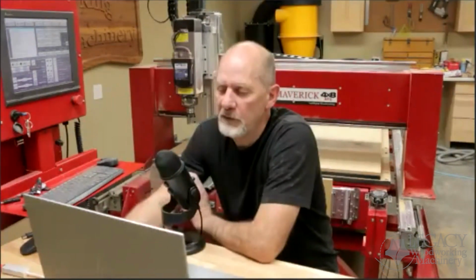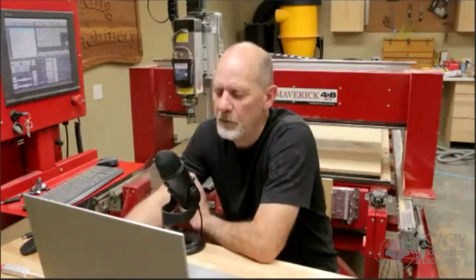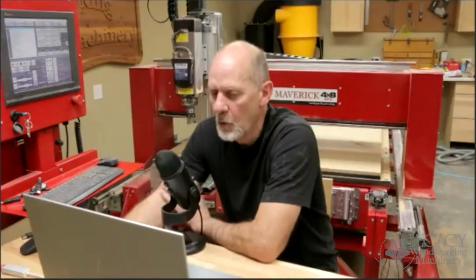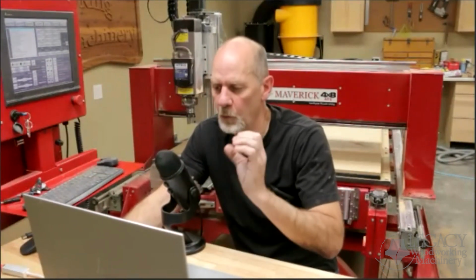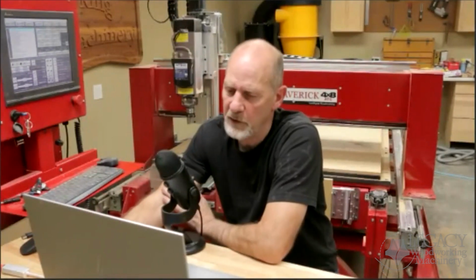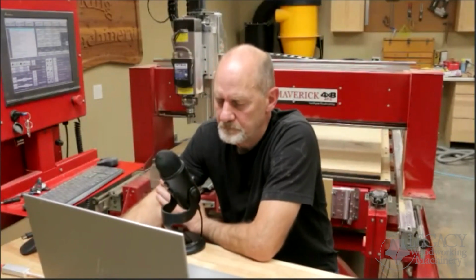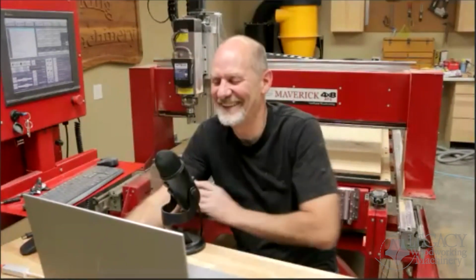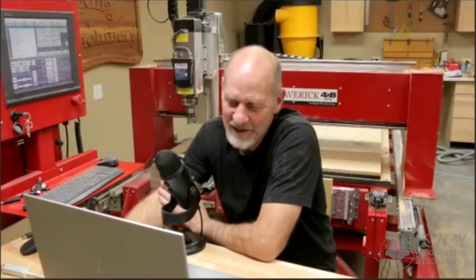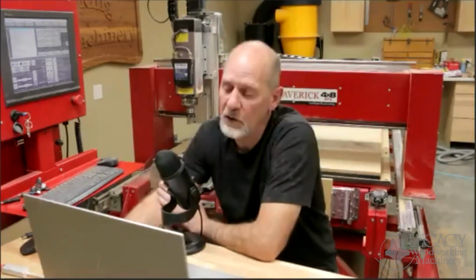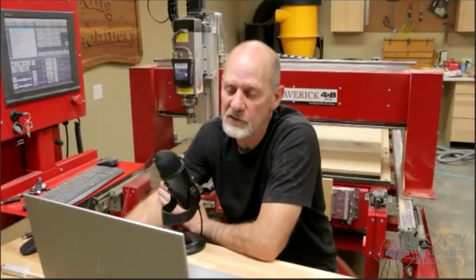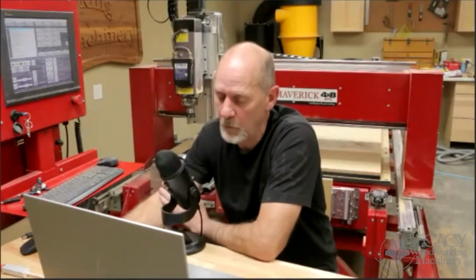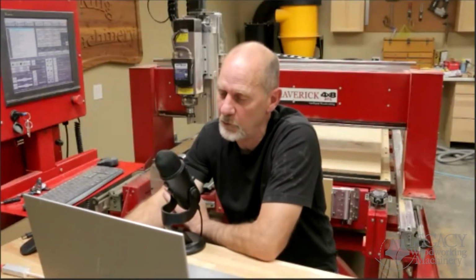This program, if you're using Mach 3 or Delta, will set the A-axis to 0 at the beginning of the program. Wherever you have it set, it will set it to 0. It doesn't matter if it's Mach 3 or Delta. If you have any questions, zero the A-axis before you run it, and then you're safe. But if you look at the code, like I showed you, if you see that G92 and an A0, that means I'm setting the A-axis, no matter where it's at right now, to 0 before I start cutting.